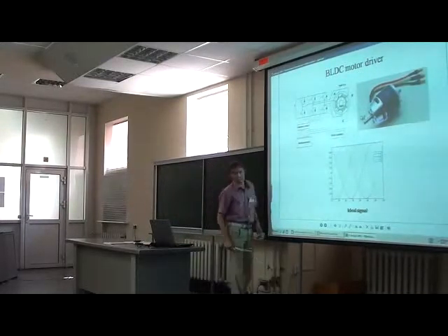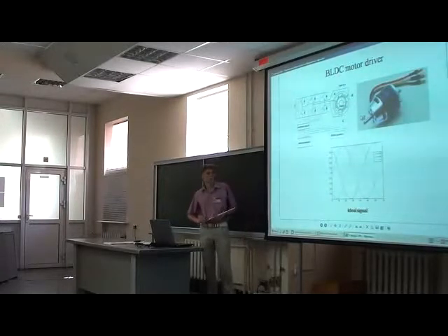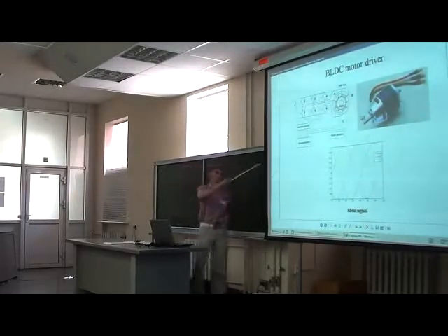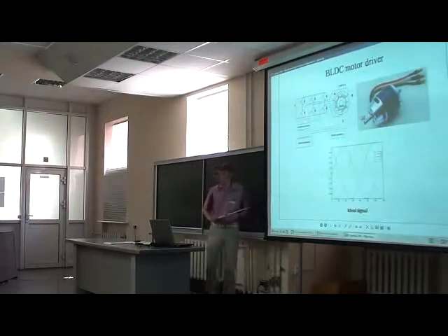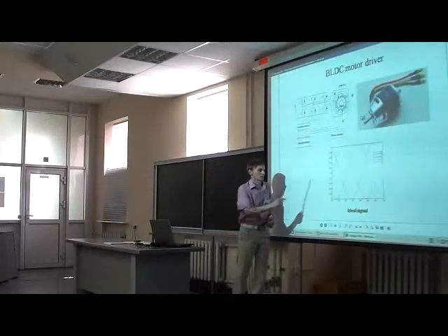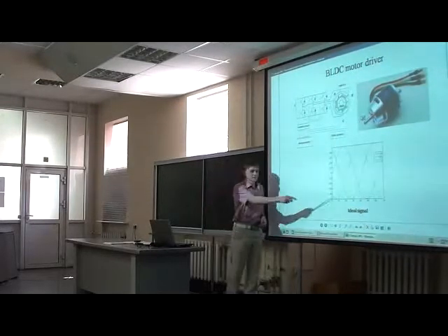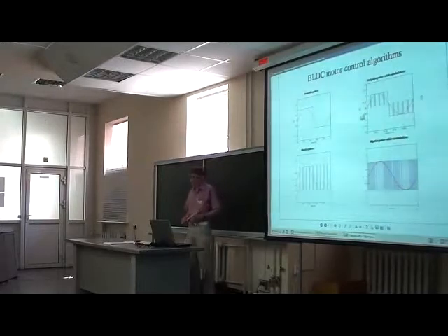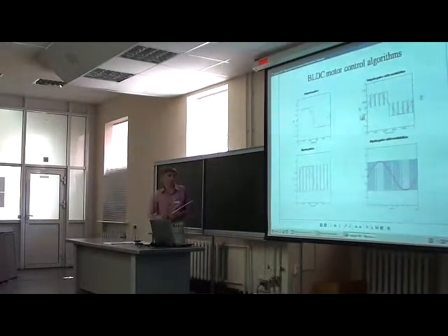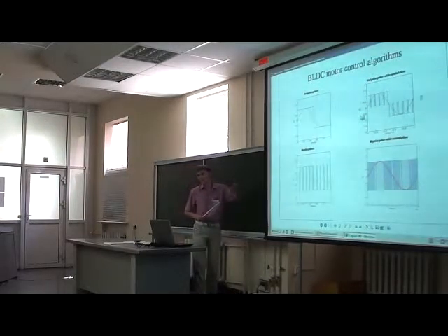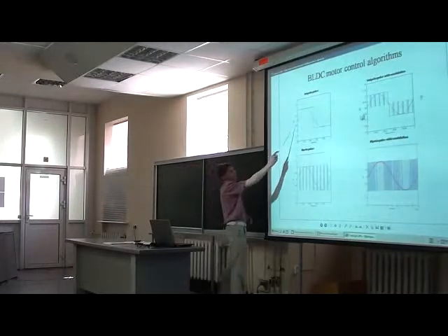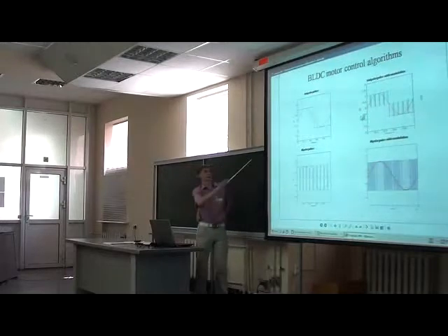Here you can see the ideal signal which we need to drive this motor. And the task of our control system is to generate the control signal near to this ideal sinusoid, sine wave. There are different algorithms to build these signals. There are 4. The first one, unipolar pulses. You can see that the sine wave is generated as a meander.